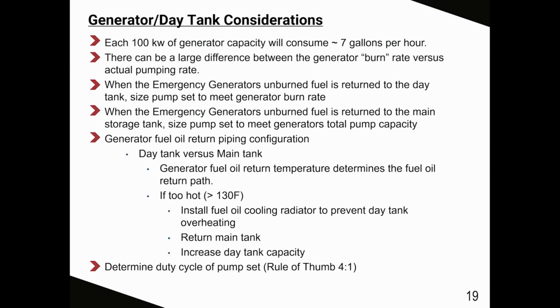Remedies for keeping day tank supply fuel oil cool. Install a fuel oil cooling radiator to prevent overheating. Return directly to the main tank, bypassing the day tank. Or if possible, increase your day tank capacity.